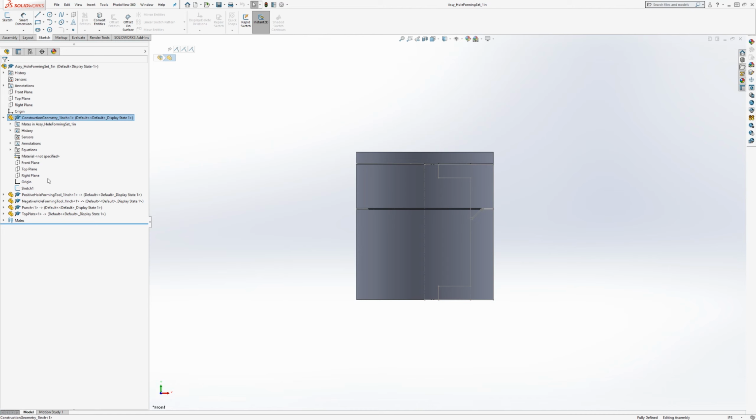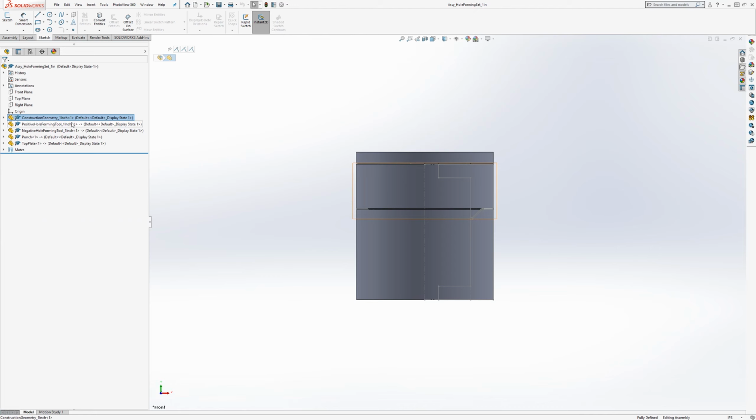So obviously in SolidWorks we can't have surfaces at the assembly level. They have to be in a part. So I've put the assembly geometry in this case in a part, but if it's just wireframe, you can also put it in the assembly. So we can see here this part is independent, and each of these parts has a reference.